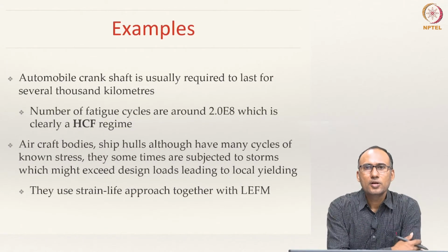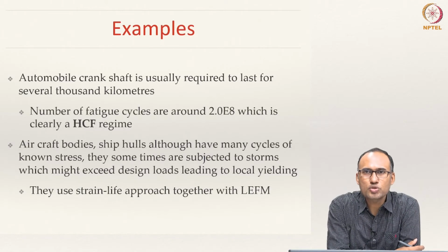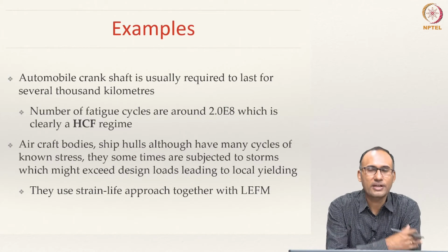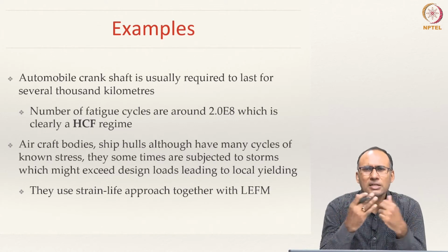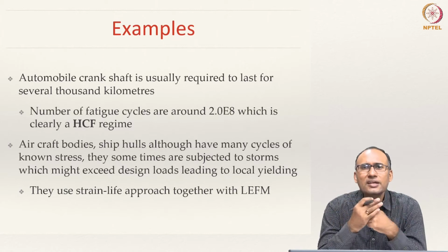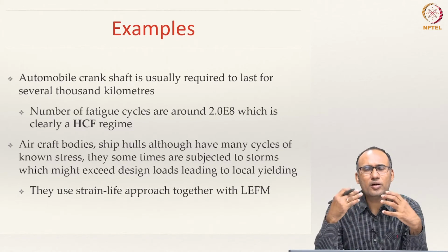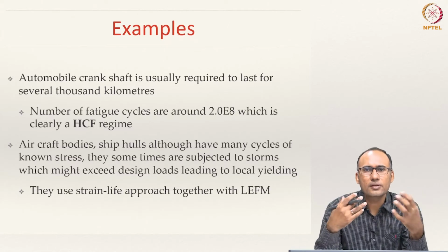We have discussed the stress life approach and the strain life approach, and we said that the stress life approach is best suited for the HCF, high cycle fatigue regime, and the strain life approach is best suited for the low cycle fatigue regime. But what are the different engineering components that actually need to be designed for one of these scenarios, whether high cycle fatigue or low cycle fatigue?